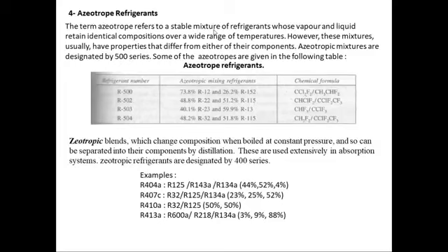But they cannot be separated by the distillation process. Even if they go through the phase change process in the refrigerating circuit, the same ratio of the two components will be there, or three components. They cannot be separated, so we call them azeotropes. The other ones which get separated by distillation are called zeotropes.